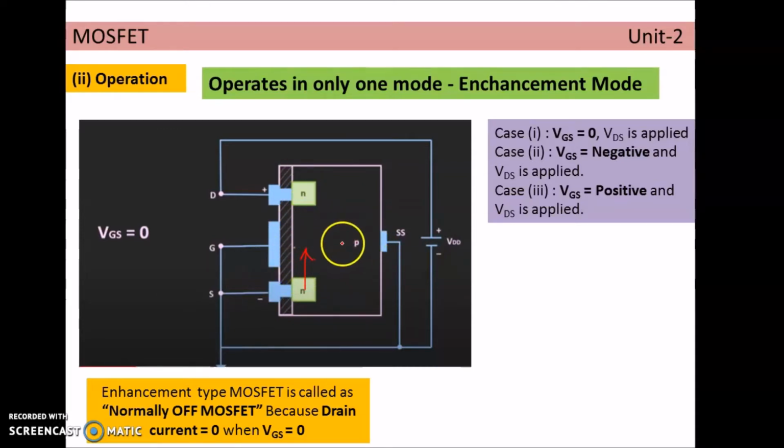In the P-type substrate, majority carriers are holes, and at the same time a PN junction is created across this N region and another PN junction is created across this N region. Due to the non-existence of a channel between these two regions, the electrons repelled from these N regions cannot get enough force to enter into this N region.